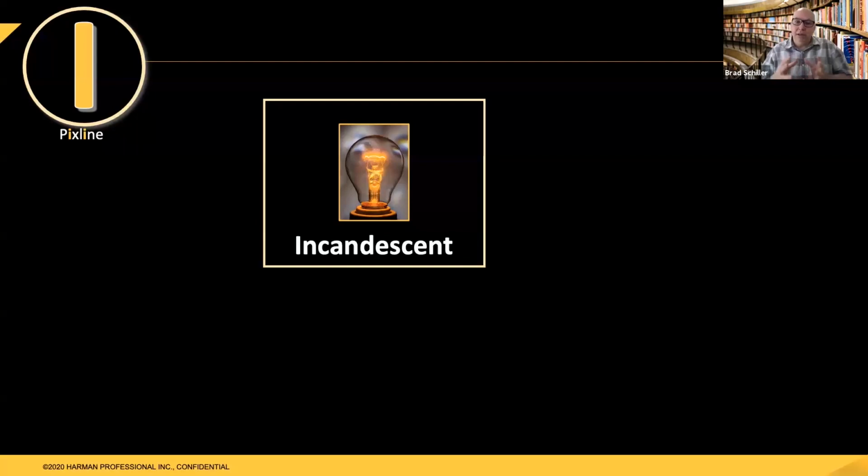And nowadays, incandescent's kind of changed to be not just talking about what the source is, but it's actually a look. So a designer might talk about, I want an incandescent look here. And basically they mean they want a 3,000 Kelvin color temperature out of the look. Also, there are LED fixtures that will emulate incandescent capabilities or looks through color temperature and also through how they dim as well.